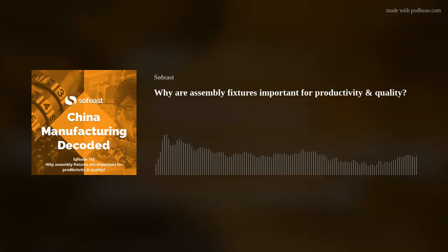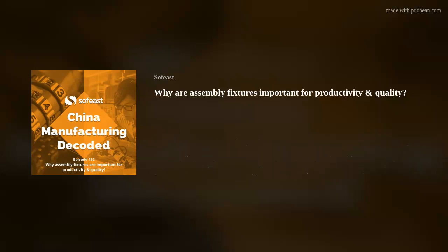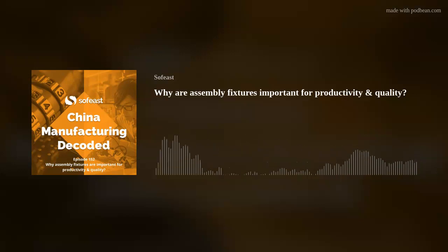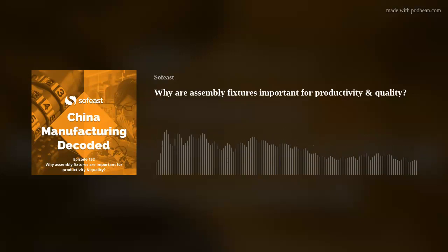Well, that's not necessarily the case. And we have to be smart with respect to our designs. From a design aspect, we need to make sure we've got an error-proof design. In other words, you can't put the two components together back to front and cause an error. There's a term the Japanese have coined, which is poka-yoke, which basically translates into error proofing. And one easy thing to do is to design a product with different size components.